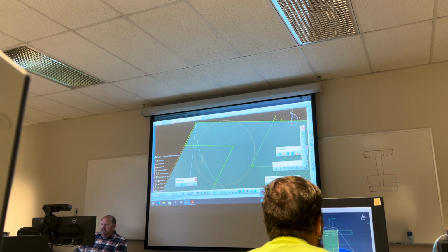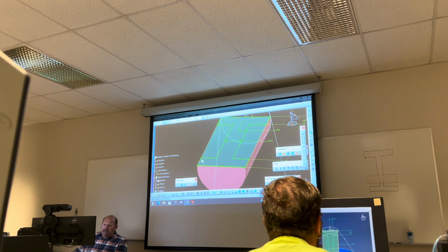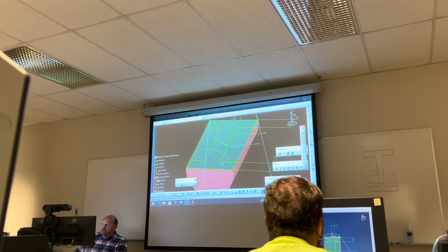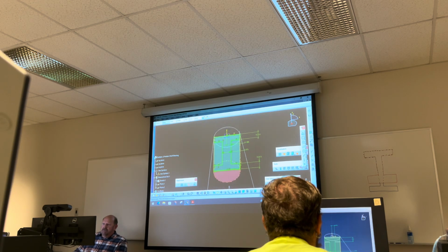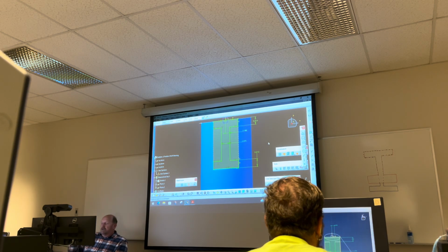Now, on the edges here, you can see I'm coincident, because I did that down here at the bottom, and my line basically lined up with that one because when I was doing the sketch, I made sure that everything looked good. So now if I go to this view, there's that top sketch, right? So we're gonna do the same exact thing at the bottom, off the plane where it needs to be built.